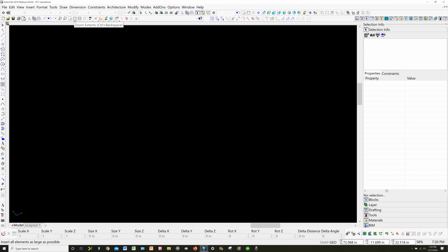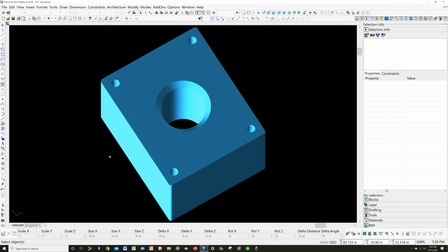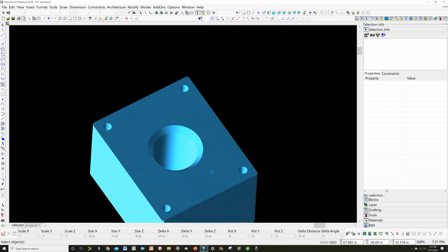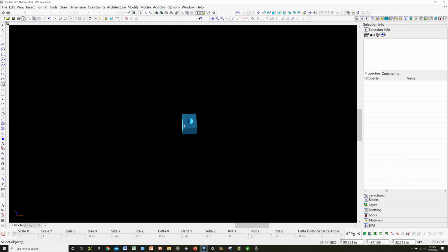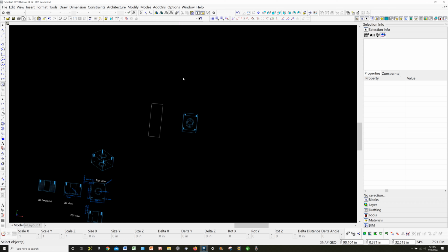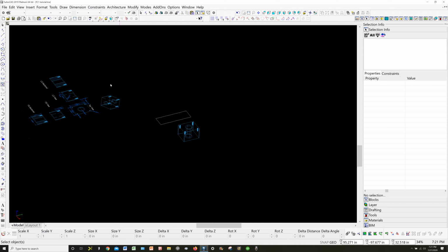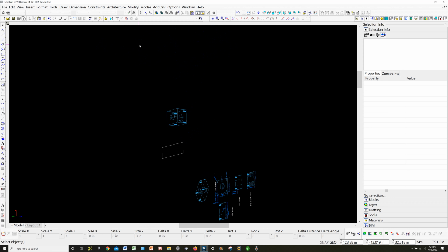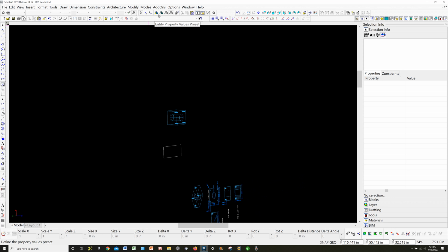and this little guy right here is used to put it in the center of the screen for you. And now that I got it on draft, I can examine it a whole lot easier, okay? And the same is true if I go to hidden line. Okay, it even gets easier to move around because it's less complex math. And then the wireframe, where all my 2D objects also get moved around. Okay, so those are the different ways of looking at it.